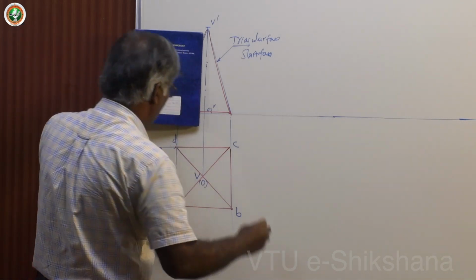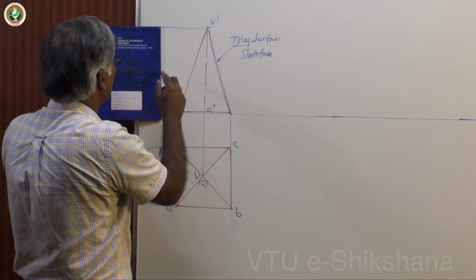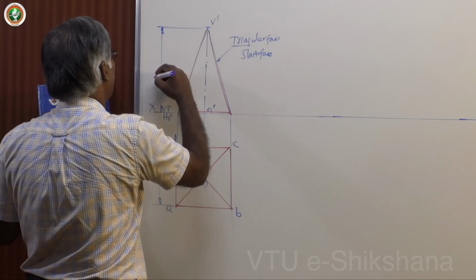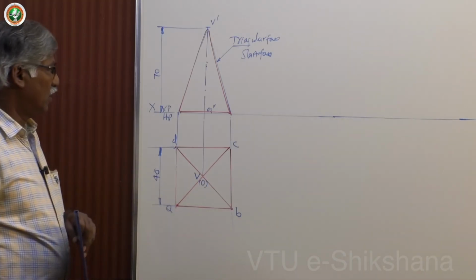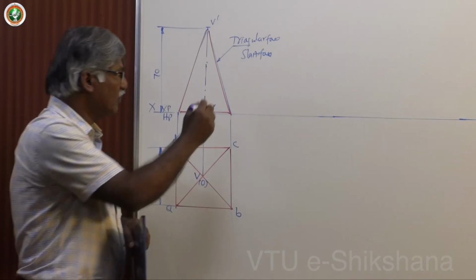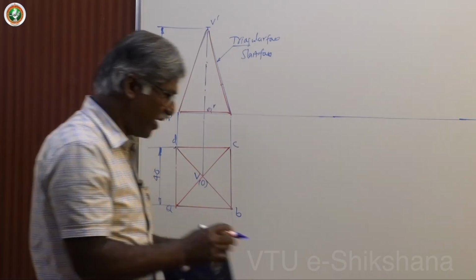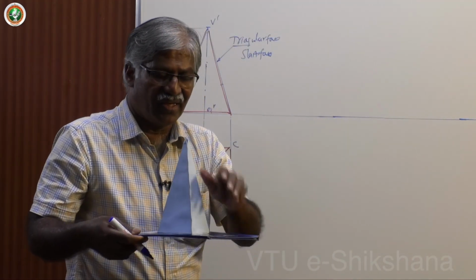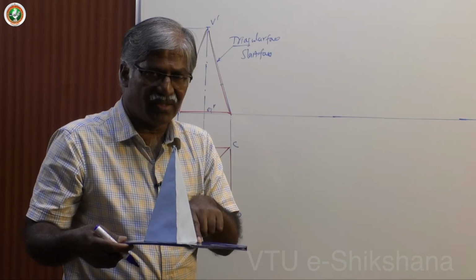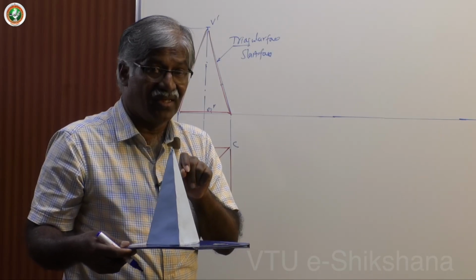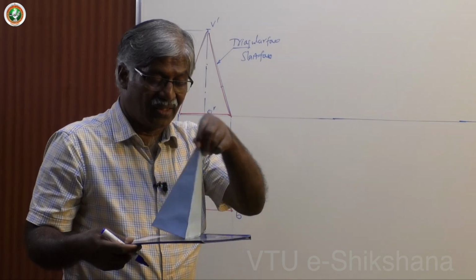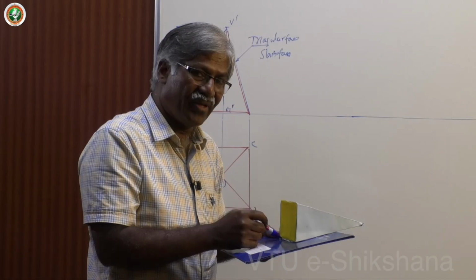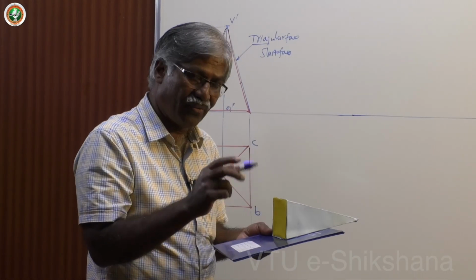Dimensioning, proper dimensioning is always required. So, it is 70. Now, I have to concentrate on the triangular face containing the base edge to be placed on HP. It never says it is to be placed, it automatically comes with that. Whenever the slant face is on HP, one of the base edges is part of the slant face.